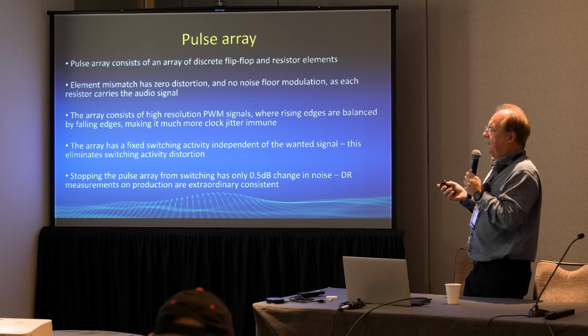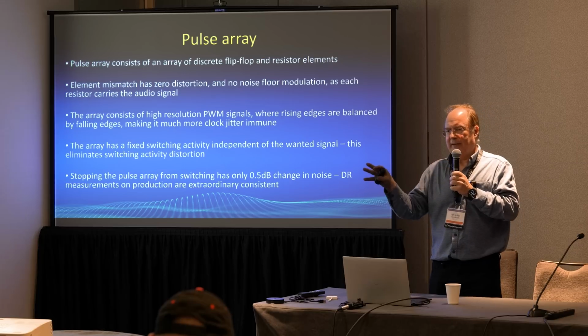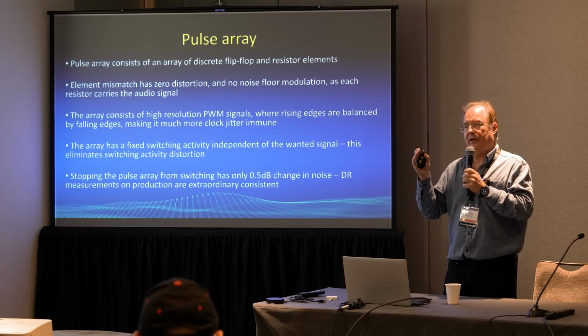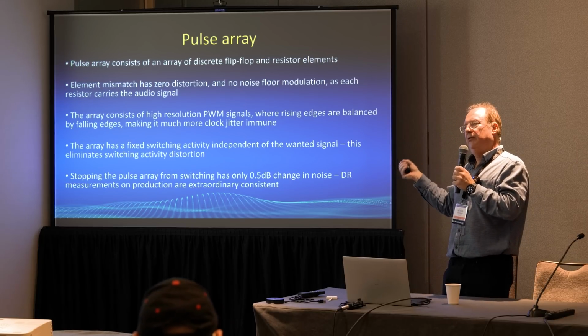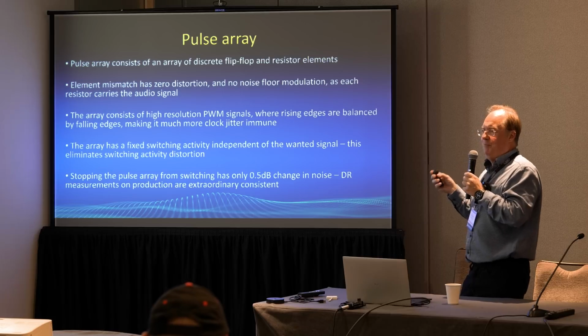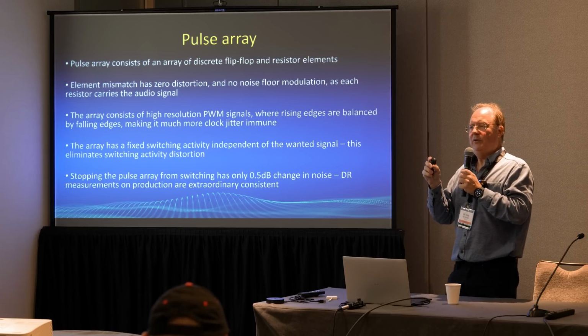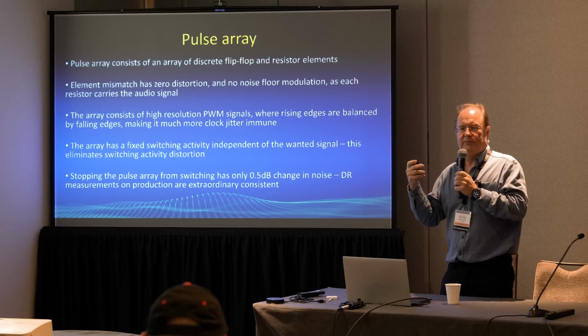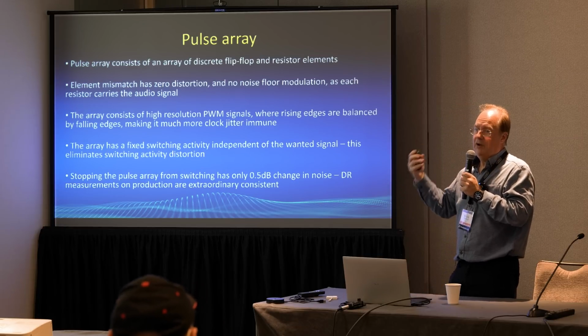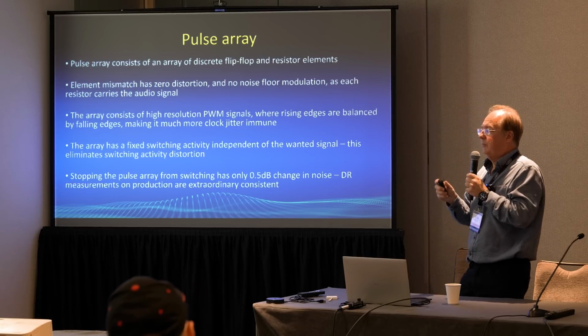The other benefit I've got with Pulse Array is that when you shut the DAC down, so you feed each individual element with DC, the noise only changes by half a dB. And that means that your intrinsic switching activity is not changing the noise performance. It's all down to the resistor noise and the op-amp noise. And that's very important.